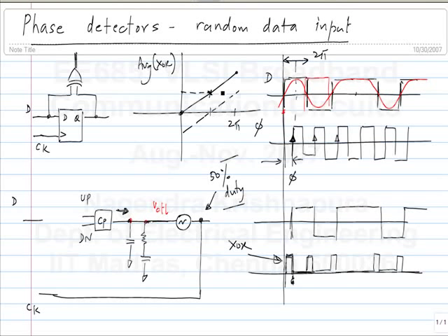Essentially I want to get the average value. But I make a flip-flop using some transistors and I don't know the exact average value. I know that I'll get a pulse, and that pulse depends on the flip-flop itself. So it would be best if I get that average value or this shift using a flip-flop itself, so that it will be exact. So how do I do that? That's exactly what we need to do. When it is shifted by pi, when the clock is aligned here, this XOR output will be half period wide. Now, we need another output which is also half period wide, and then that will cancel out this one.